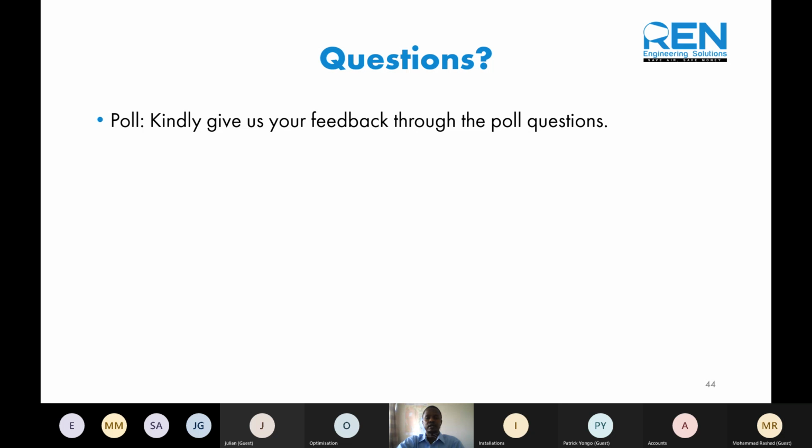So the first question that is here is, if I don't repair or upgrade any of my compressed air equipment, how often should I establish verification procedures? As I mentioned during the presentation, at least a single test a year will help you determine if all the engineering controls that you have put in, such as having oil-free compressors, having filters at the point of use and in the compressor room, are working.